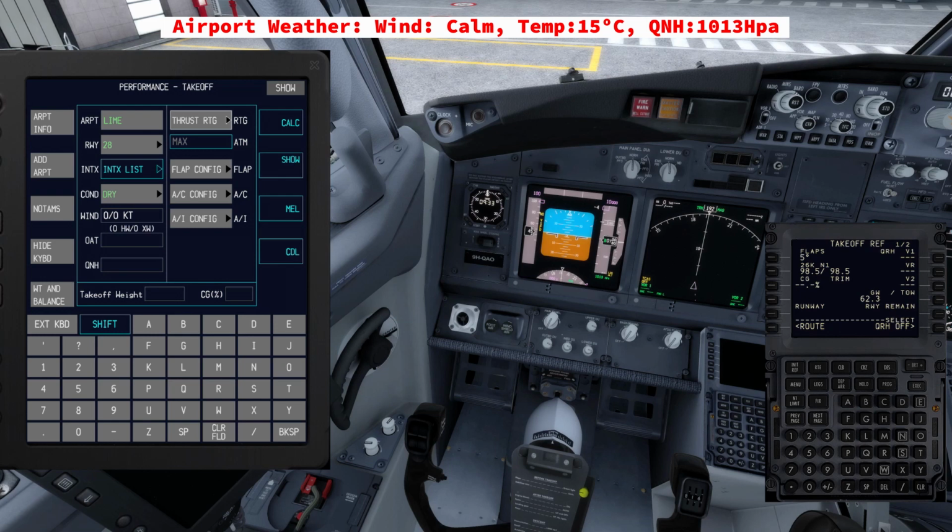is reduced, because the maneuverability of the aircraft during the takeoff roll is actually reduced. So depending on the condition of the runway, you should check the crosswind component and make sure that you can actually take off. Okay, then we've got the outside air temperature, and you should set that one.